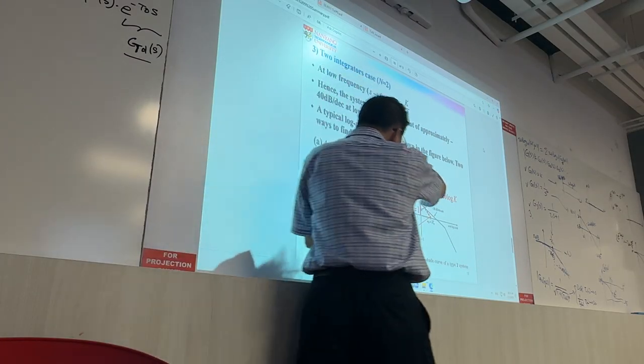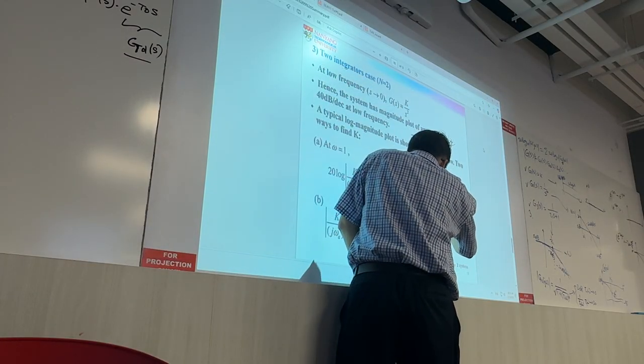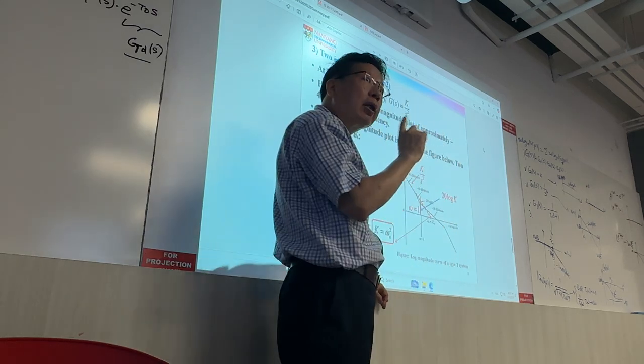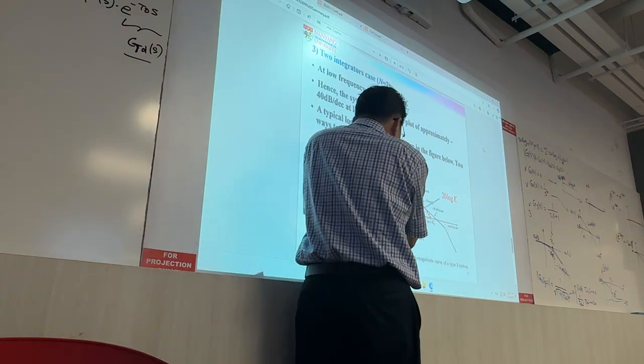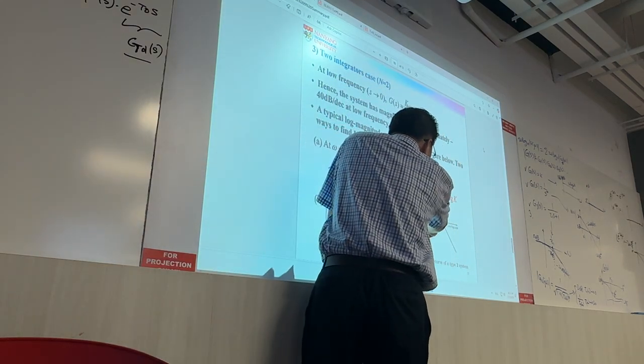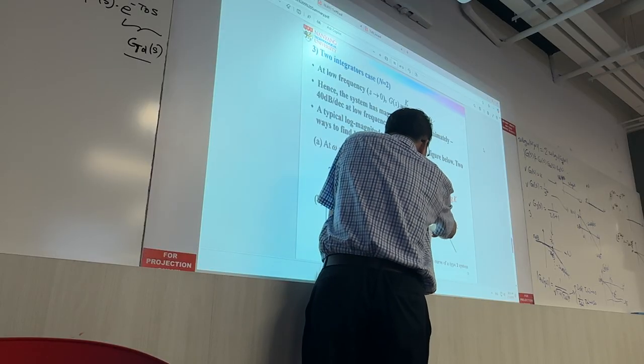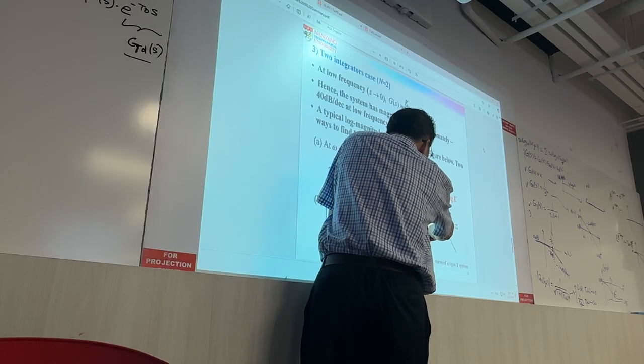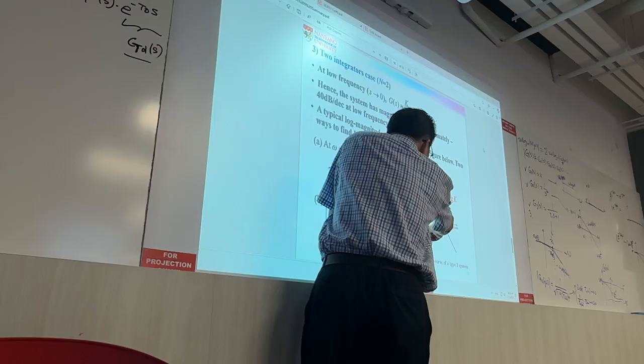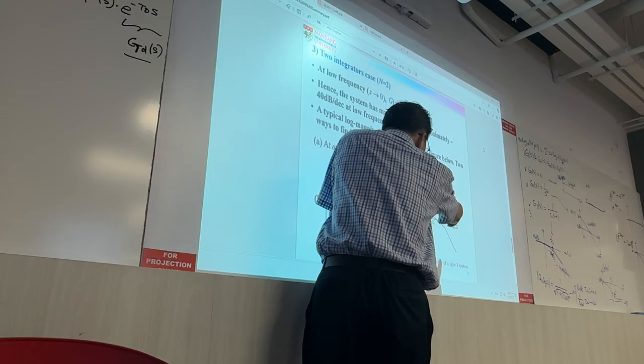But when you extend the left portion and cut here, it's not going to be the K value, but it's related to the K value. So you cut this frequency at 0 dB, you read it out, it's actually related to the K value by a square root.